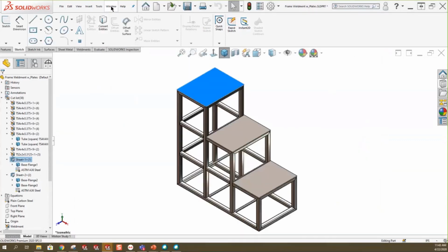I'm going to go ahead, and one last thing I want to show about this. You guys may talk about this. Why did I do this as part level? Why don't I just build it all at the assembly level? If anybody's ever tried to build what's called in context at an assembly level, you have top down and bottom up assemblies. Bottom up is I build all my components, bring them together in the assembly, piece it together with my mates, and make my assembly.